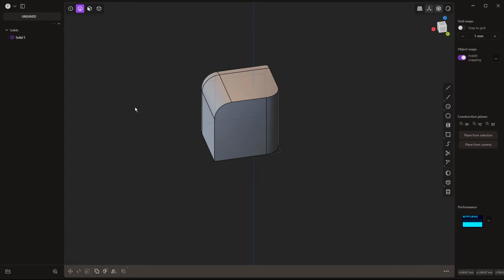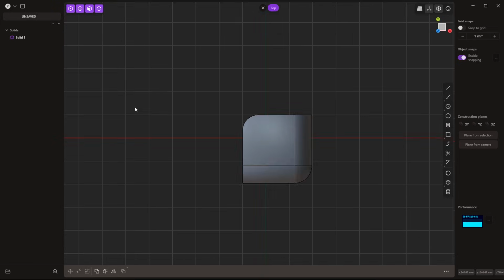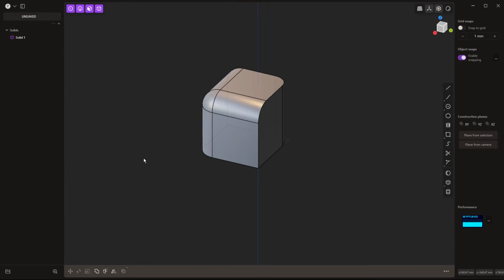Now, in addition to that, the numbers across the top of your keyboard will let you pick what these are. And if you hold down the Shift key, you can add to that selection or remove from it. And you can also hit Tab or the number 5 on the keyboard to turn them all on. I think that this is incredibly important, making sure that we're comfortable with going to our different views and making sure that we're comfortable with changing our selection filters on the fly. The rest of the shortcut keys we have are great to know, but honestly, we can find them in other areas. Going back and forth between our selection filters, those are really going to make a big difference.